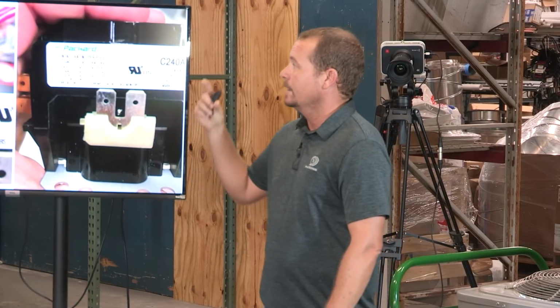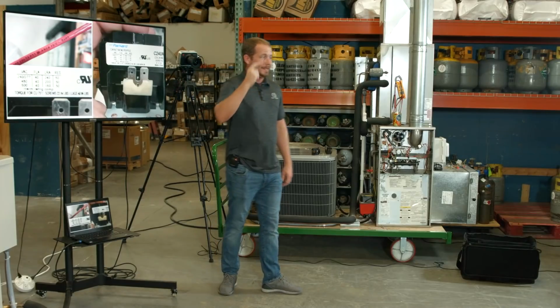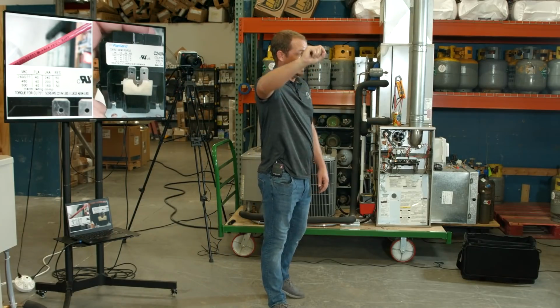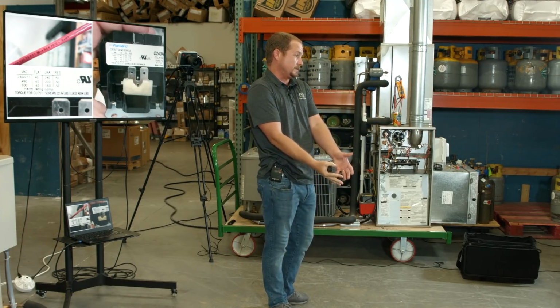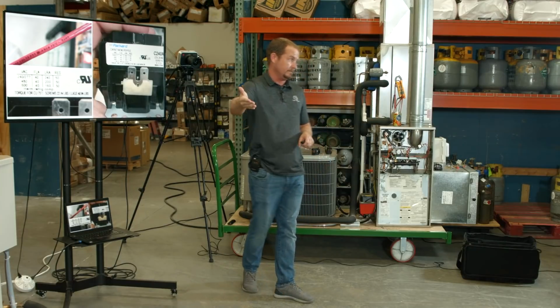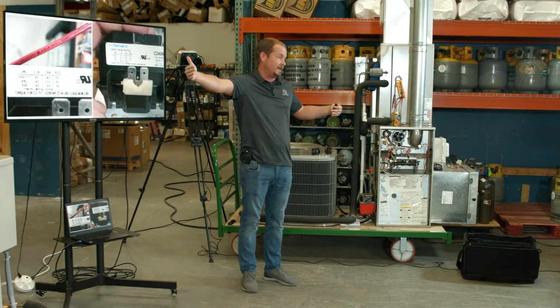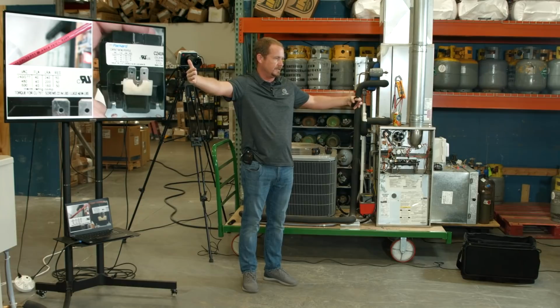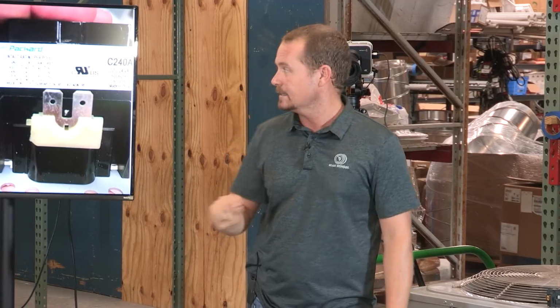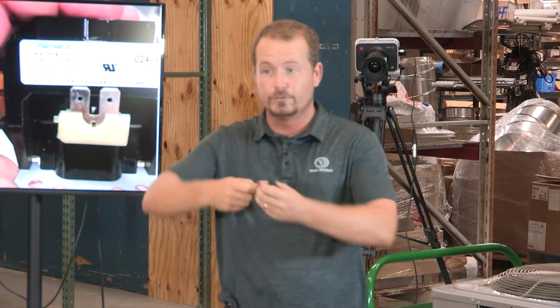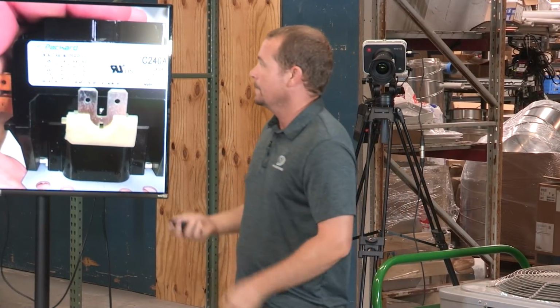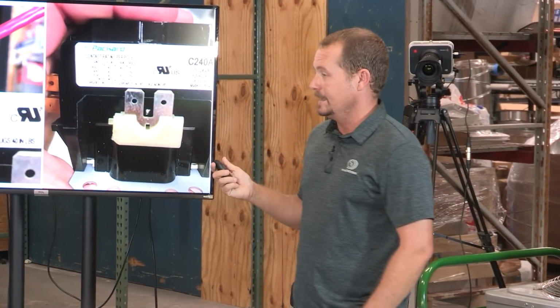So the point being that we worry about voltage drop that has to do with length because that results in voltage that's too low to the unit that could cause problems. That doesn't cause overheating. Too long of wires doesn't make things overheat in terms of the wire or conductor itself. Too small of wires does, and insulation ratings that are too low do, or wires that are run through too hot of spaces, or too many wires run together. Those are the things that cause fire issues, and therefore those are the things that NFPA is concerned with.